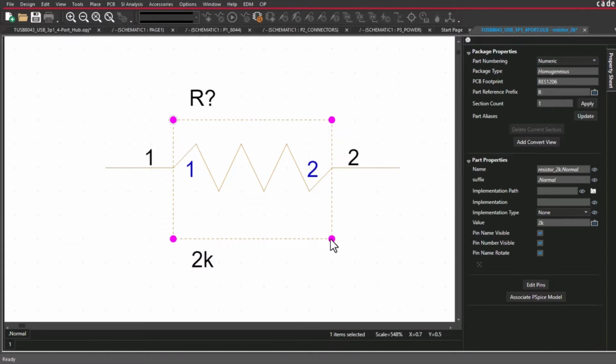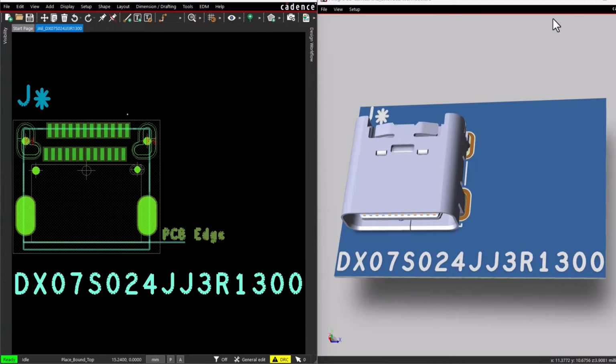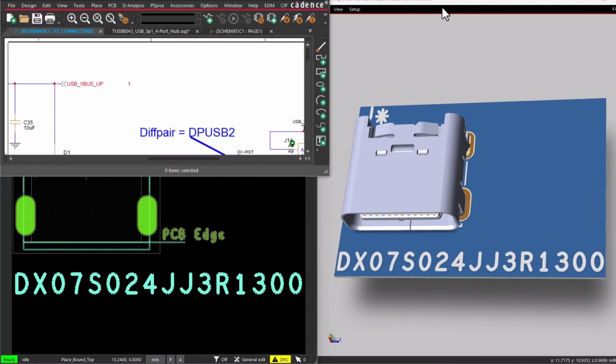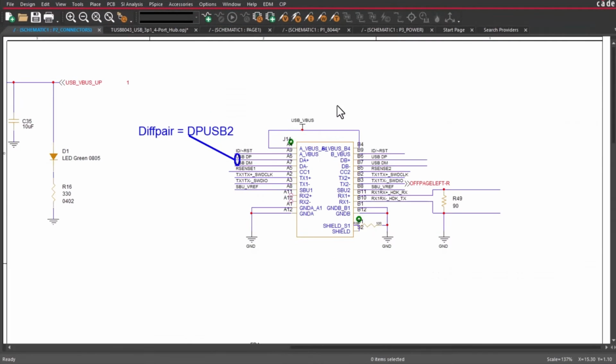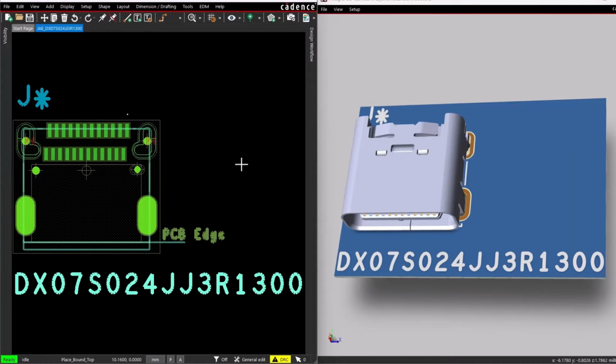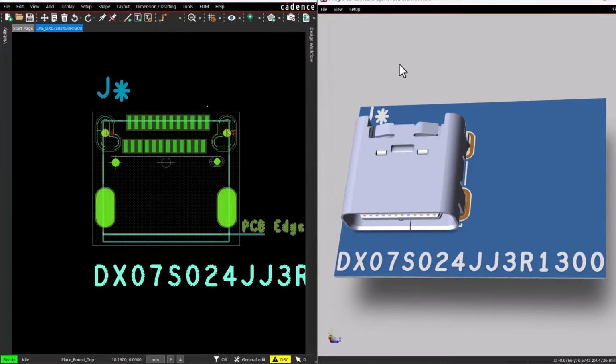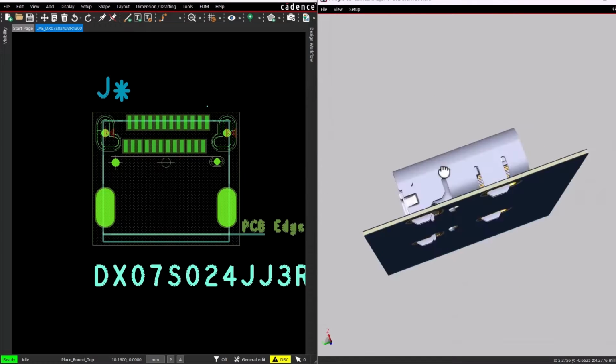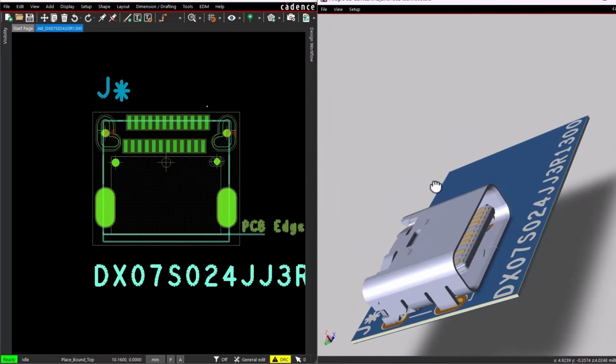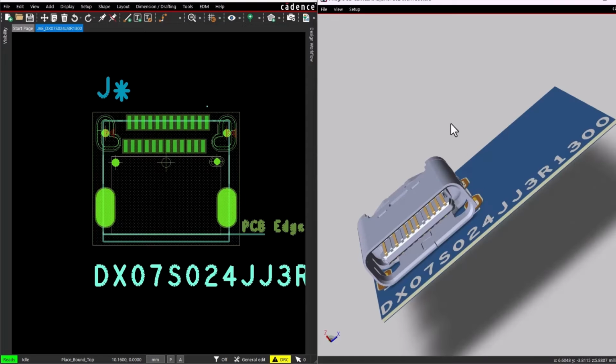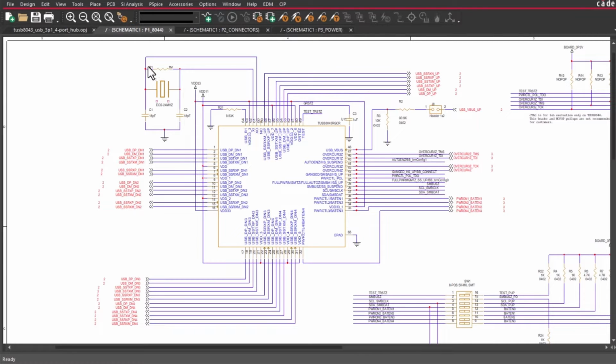Okay, the next domain would be PCB footprints, to model the area underneath the part once it's actually laid onto a printed circuit board. So that's where you would get PCB footprints to model that. And then you have 3D models, so we know what the part looks like, and so that it's more realistic. Nowadays, you definitely have to use 3D models to verify that your part will fit properly, not just on a printed circuit board, but within the overall design and the form factor.